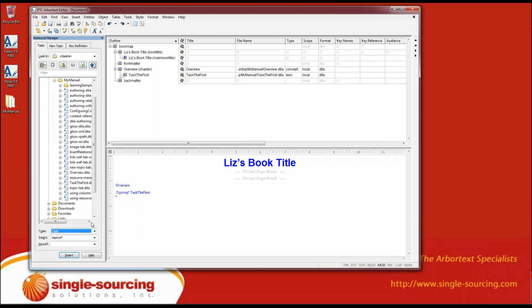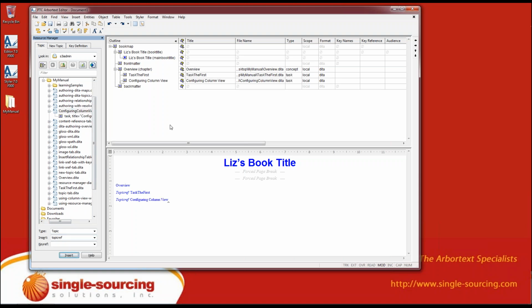We're going to insert only topics. We're not going to insert a map. And we're not looking for an image at this point, and we're not inserting a PDF image, which we could do because Arbortext will let you use a PDF to insert in your map, and it'll insert those pages right along in that location. So let's put, here's a great one, configuring column view. Very handy tips. This is the sample content that comes with Arbortext out of the box. We can see that it's a task type, and we're just going to insert it right there in our chapter.